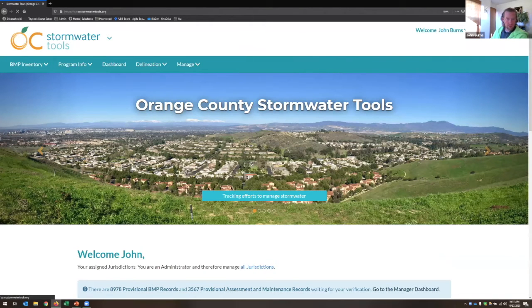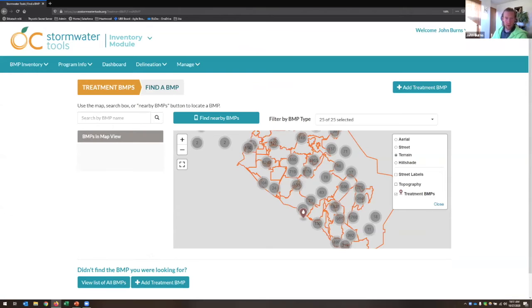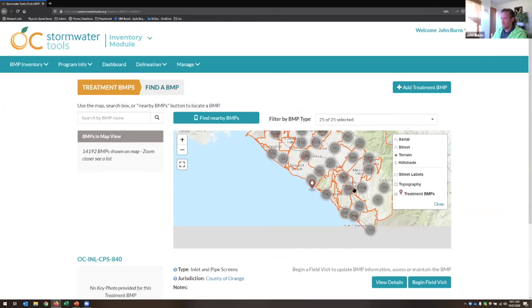So the second part, the score does not automatically decrease annually. The scoring is done in response to the observation. So depending on how often you'd like to assess your BMP, if you're going out and assessing it and seeing a material building up or damage to the BMP, that's what would drive the score decrease. There's not an annual degradation component that's built in, although it is an interesting idea, and I could see that being a part of a program design, that if you're not assessing your BMPs because you can't get to them all, you might want to assume some degree of degradation.